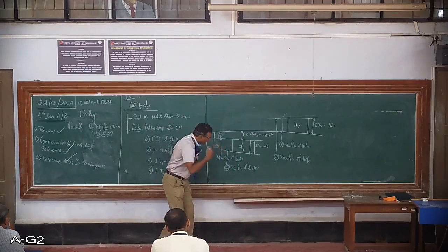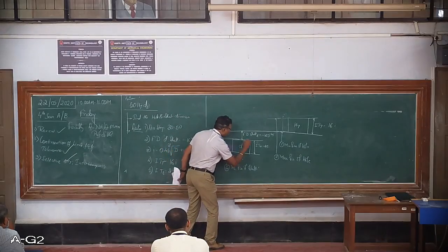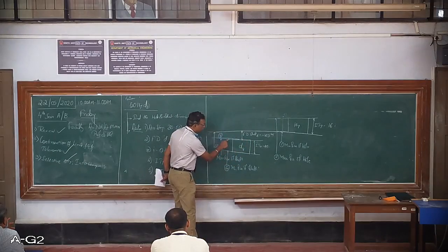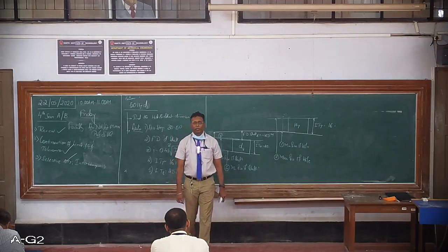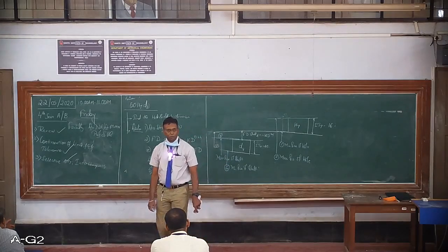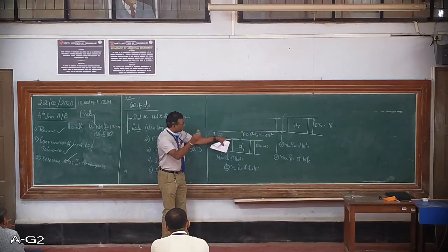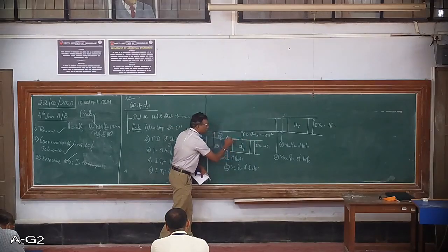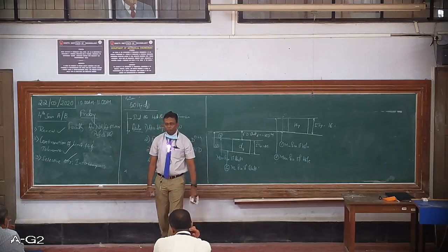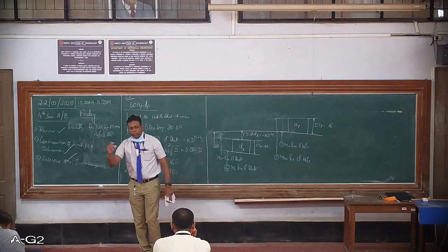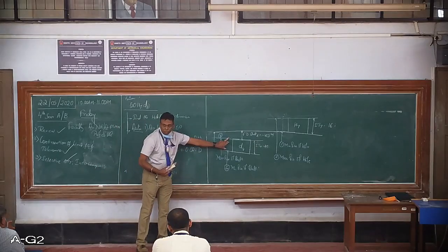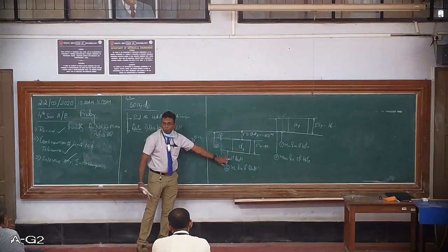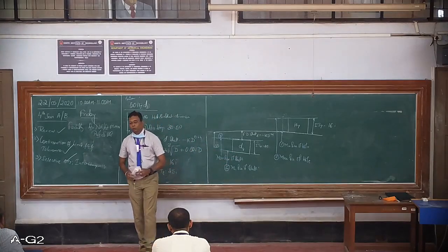Next, exactly opposite is with respect to shaft. What is the maximum shaft? See, this is the maximum material for a shaft, this is the minimum material for the shaft. If the shaft is anything less than this, we cannot add any material to the shaft and reuse it. It is not possible. If by chance you get a shaft which is bigger, one thing it gets rejected no doubt, but we can still work on that. We can send it back to the machining and use it if the tolerance level is within these two zones. But if the given shaft is less than the smallest allowable size, obviously it goes for rejection.